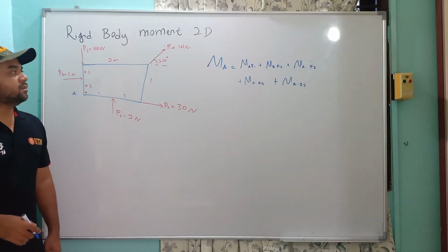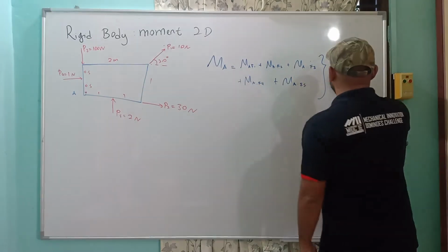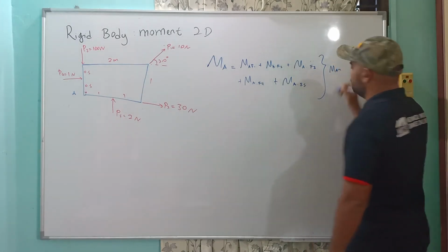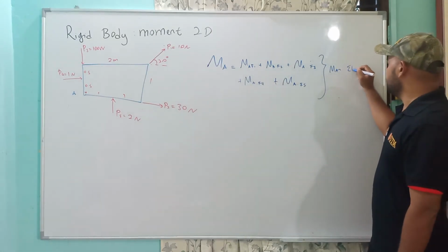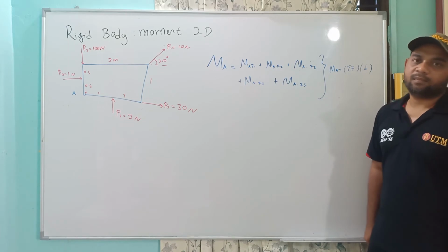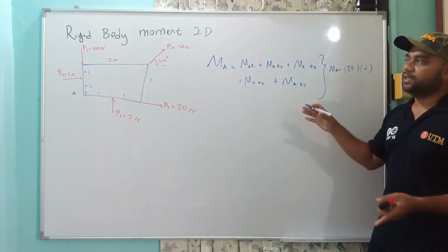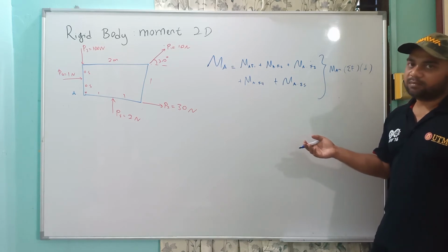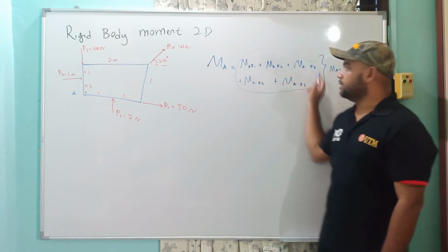Okay, you can do it that way, or you can also do it as moment A equal to, you make the sum of this force first, sigma F times the D. But this way you have to find first what is the sum of force, and later on you calculate. But normally I will use directly this one.